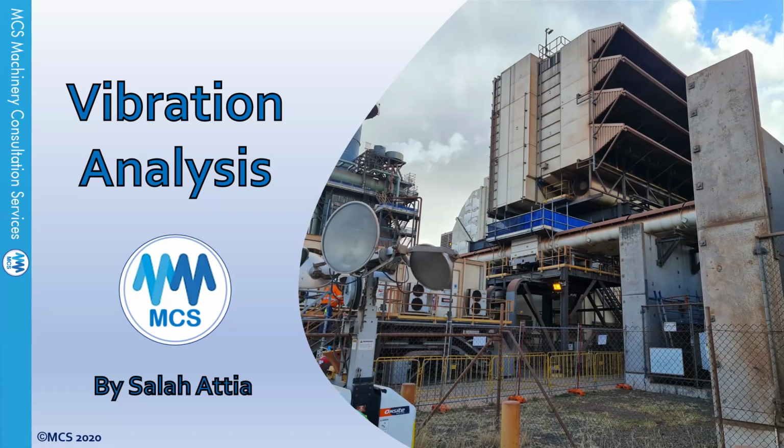How can we reduce piping vibration? This is a very generic question. This can be done by doing ODS, modal analysis, or motion amplification, and you see if you need to add some stiffened supports at some points or locations, and that will be very helpful to reduce the piping vibration. There are many reasons, even the process.